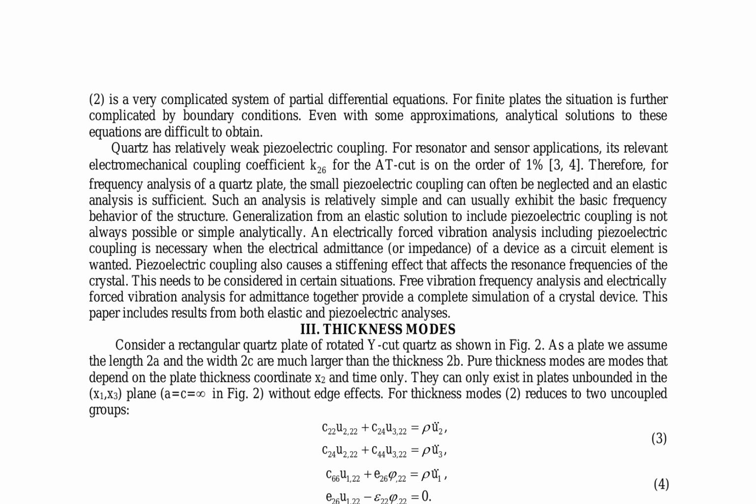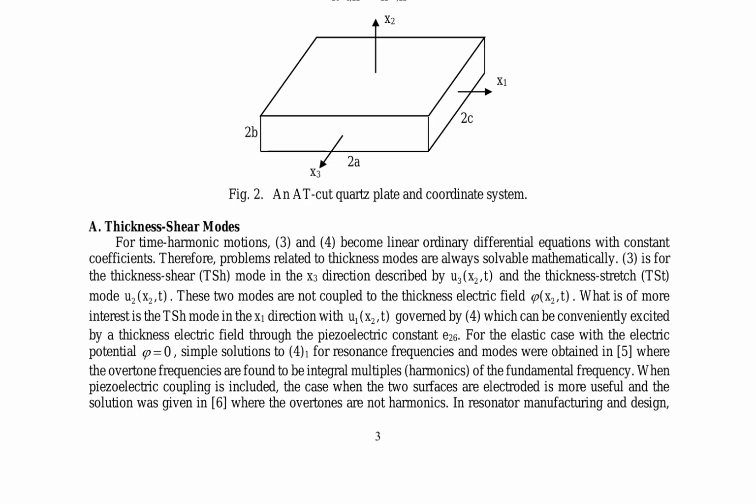The paper focuses on thickness modes in rectangular quartz plates, reducing the system to uncoupled groups of equations for thickness modes. The solvability of problems related to thickness modes is mathematically tractable, and the thickness shear mode in the x1 direction is significant, as it can be conveniently excited by a thickness electric field. The discussion also highlights the difference between elastic and piezoelectric analyses, including the effects of piezoelectric coupling on resonance frequencies.